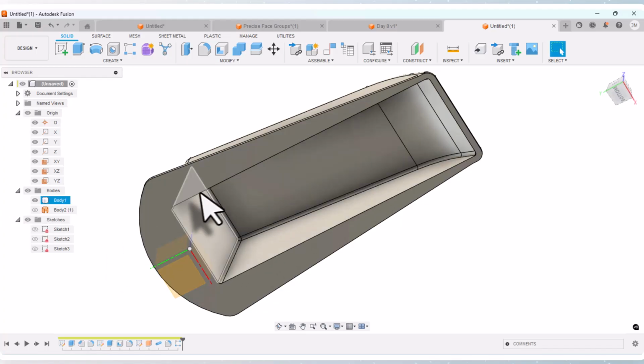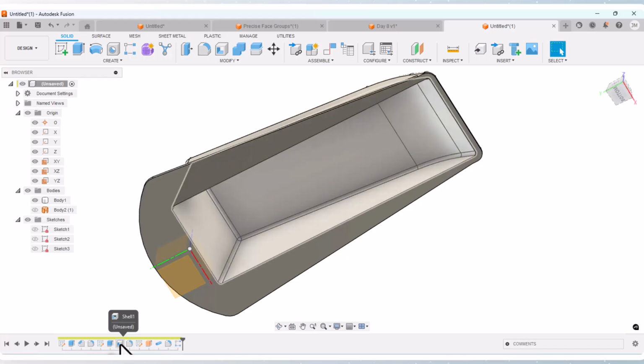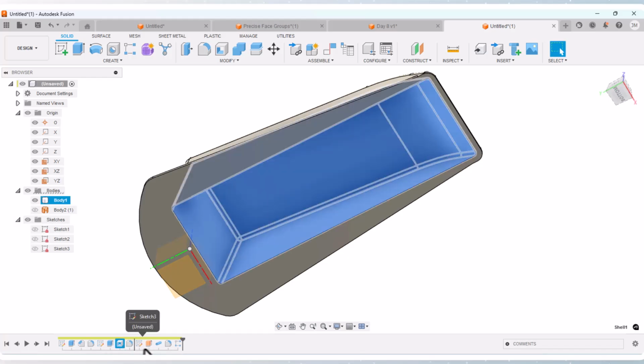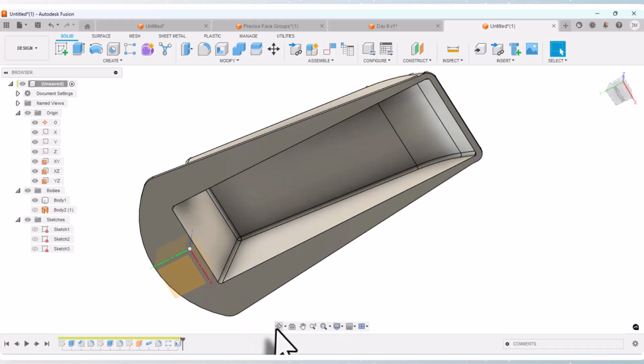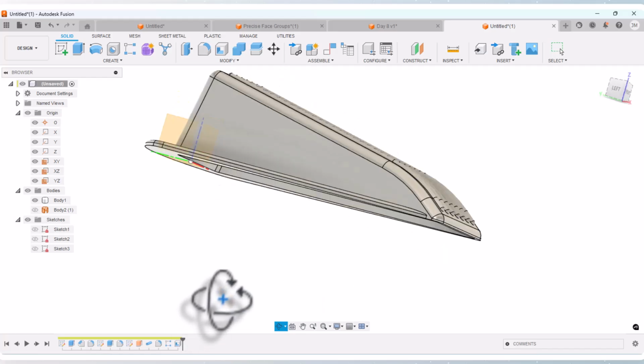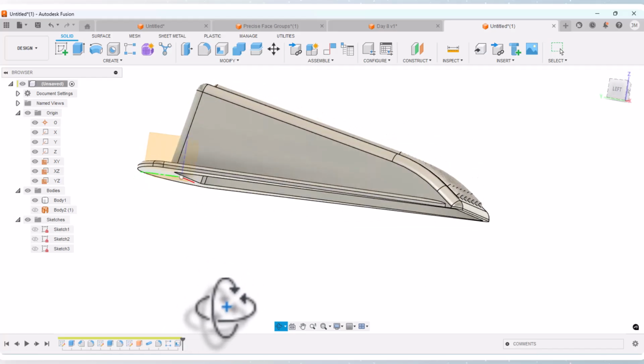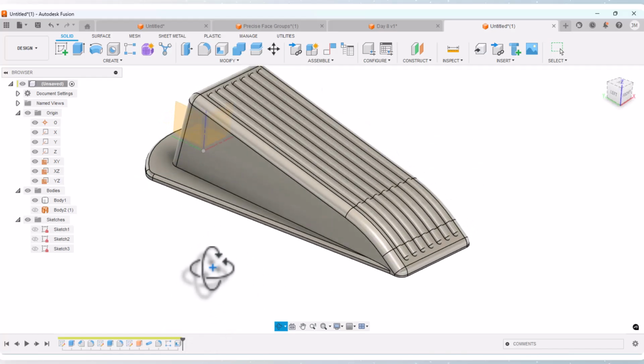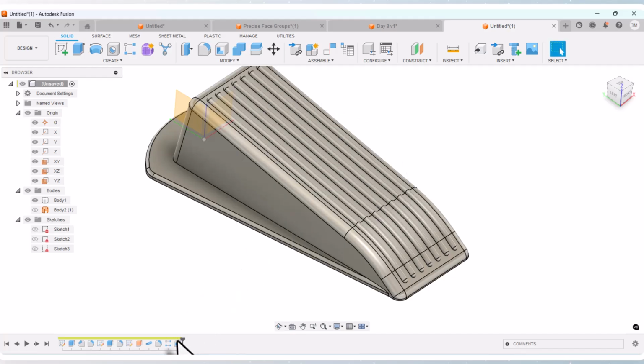Let's put that fillet in, but I'm going to drag this shell feature and see if it will give me a failure if I drag it in the timeline. I'm going to drag it all the way down here, and so notice no failure. If you see any yellow or red highlighted issues indicated in the timeline, you've done something wrong. Undo it immediately and figure out what the problem is. Don't just continue working with red or yellow highlighted items in the timeline. I want to do the fillet before that shell feature occurs.